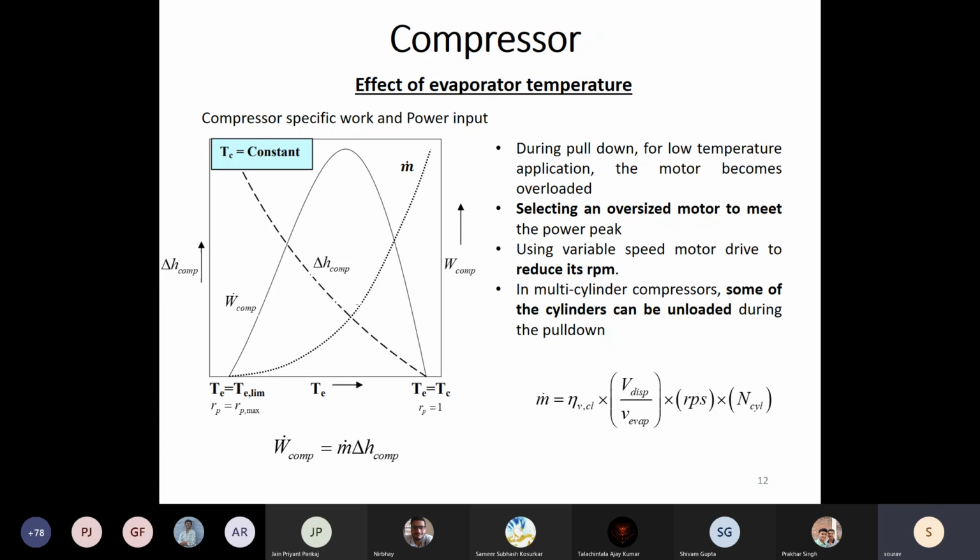So right now, what I understand is most of the manufacturers are trying to educate us that in order to reduce the power consumption and help your AC operate at its rated capacities, it is better to provide a set point of around 24, 25, not lower than 24. You will see there is a label that 24 is the best operating condition, because 24 will give you a decent amount of thermal comfort and it will not reduce the capacities and increase the power consumption of the system.